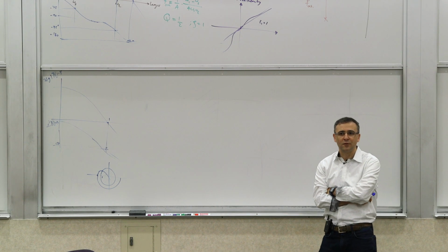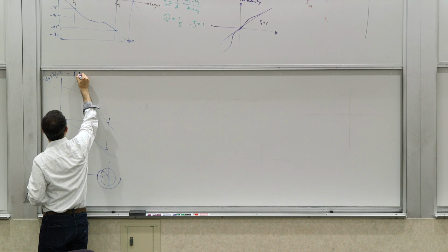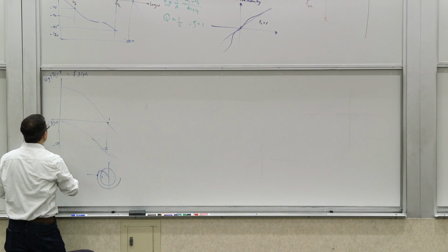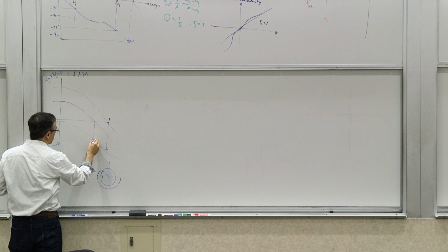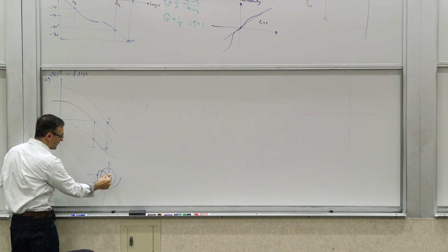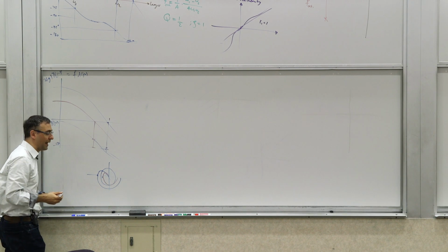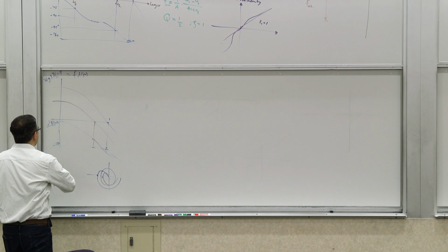If you make f smaller, because this is really f times A of j omega, then instead of being on this plot, my magnitude plot would just scale down. I would be on this plot, and then I would have sufficient phase margin. It's tantamount to scaling this whole thing down in Nyquist, so you don't encircle the point -1. So this is by making f smaller.